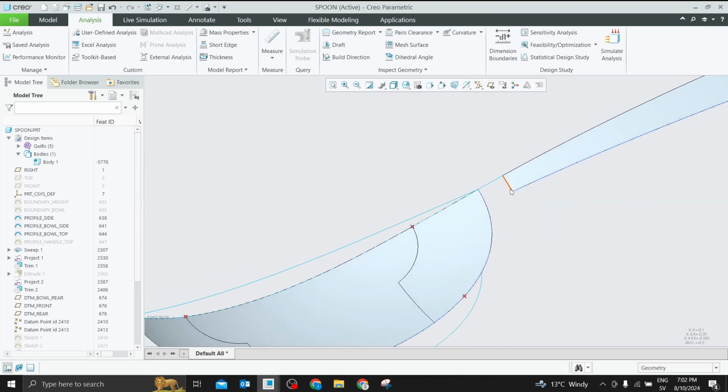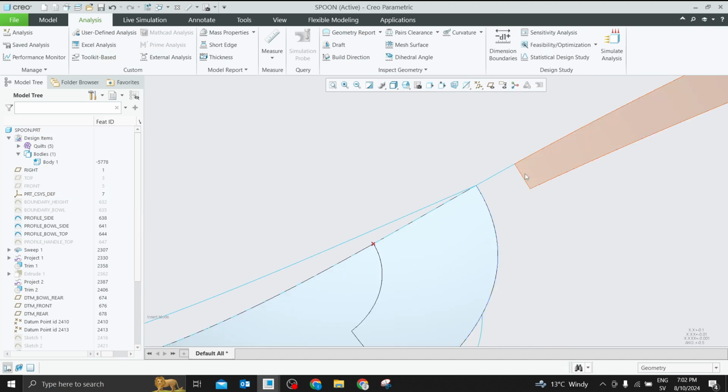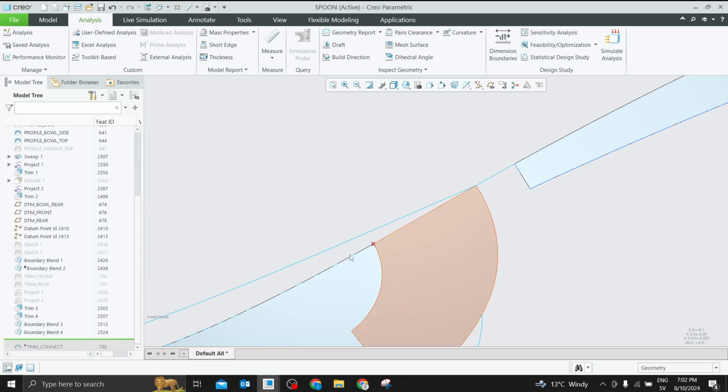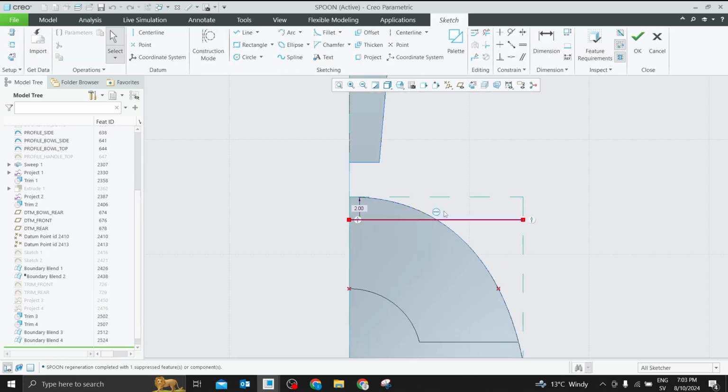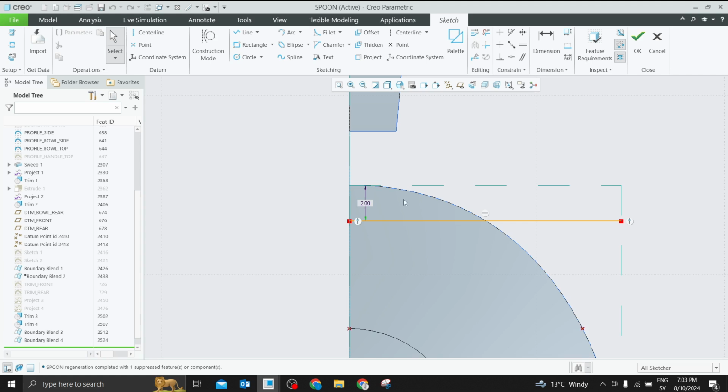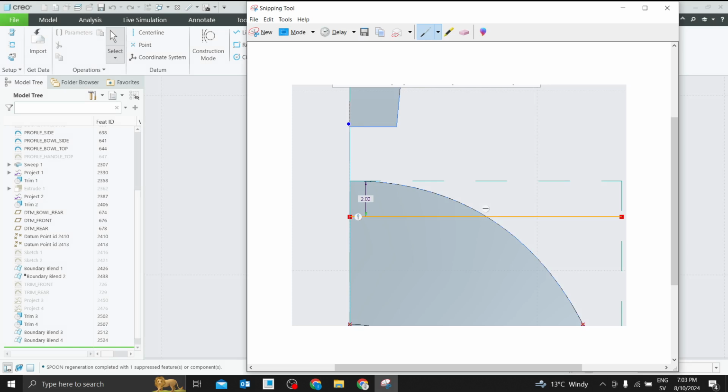Next, we need to connect these two, this to this. But we cannot connect them in a surface model. Try to make sure that whatever edges or curves you are connecting, they are similar. I need to look for a flat surface here, a flat edge. Therefore, simple, I'm going to chip off. I have a sketch already here. You create a straight line to chip off, okay? Because I need a straight line, another straight line here.